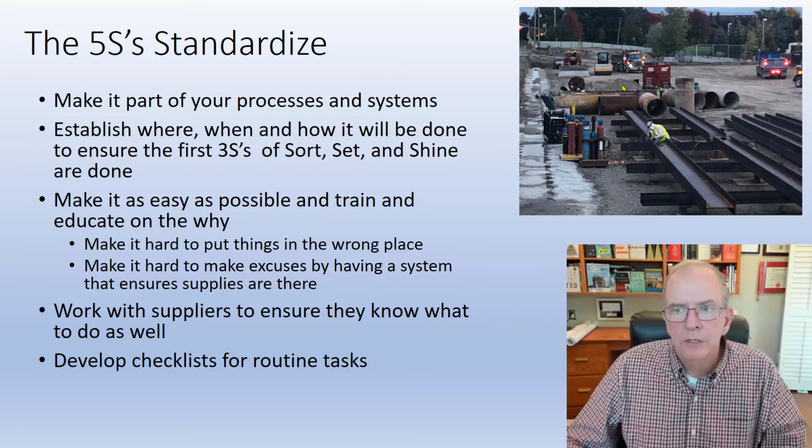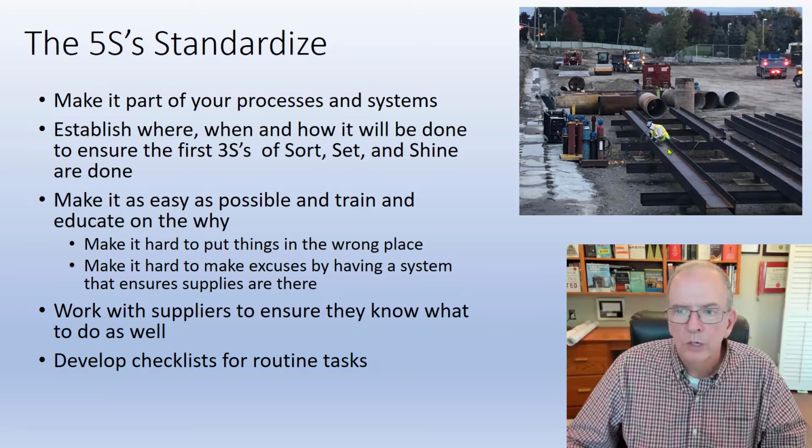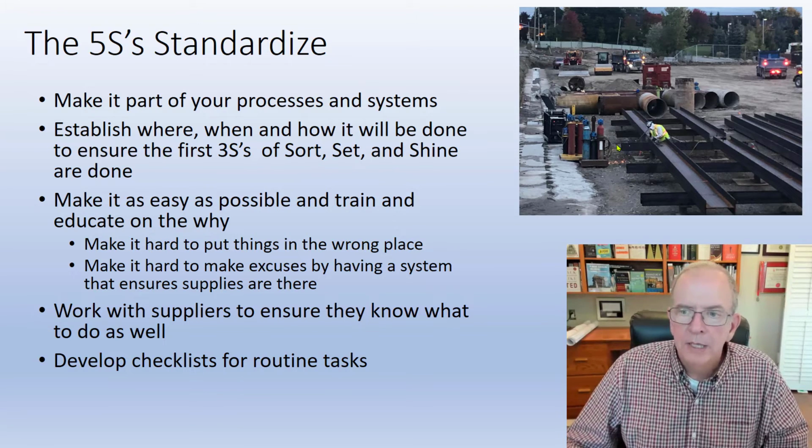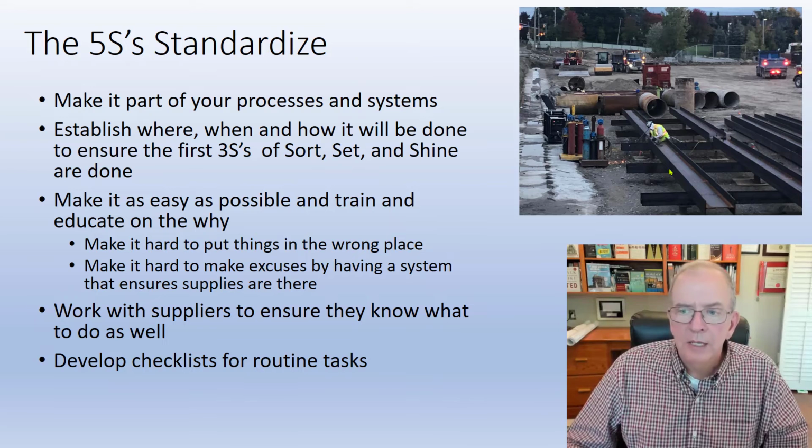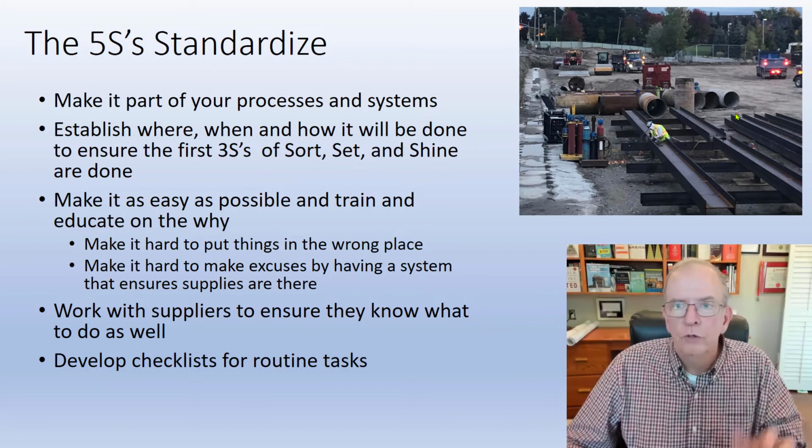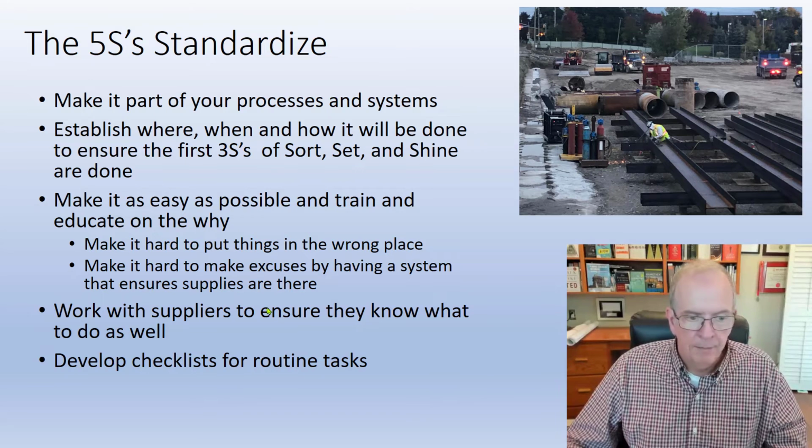I put this one here because this is a very well organized site. You can see even ergonomically how the worker set themselves up so that it's right at waist height, which makes it easy to work on these pilings that they're going to be putting along, these soldier pilings. Makes it a lot easier for them to work. And even the road here, they're constantly leveling it so there were very few divots in it, even though they're excavating this all out for a deep foundation. And it makes a big difference.